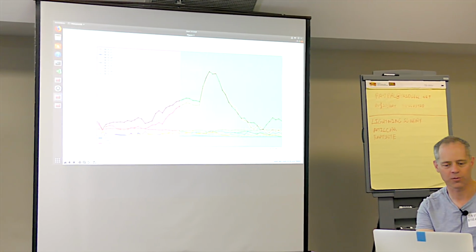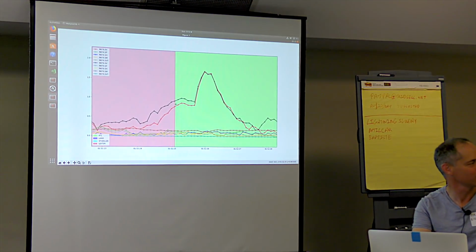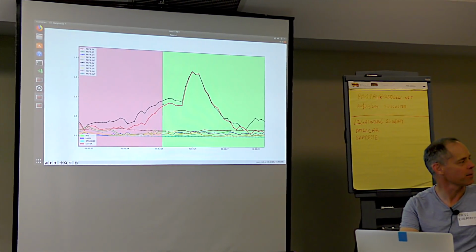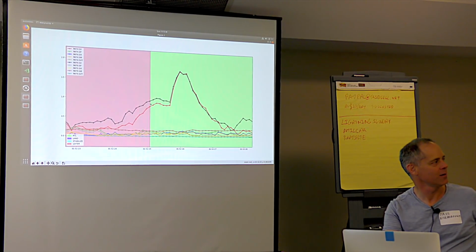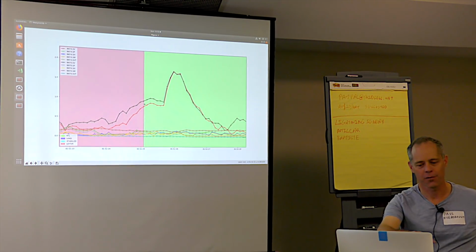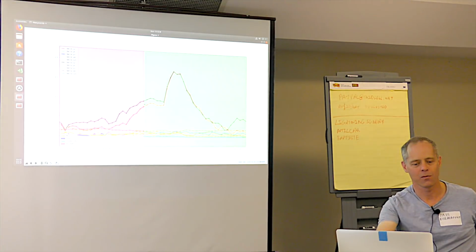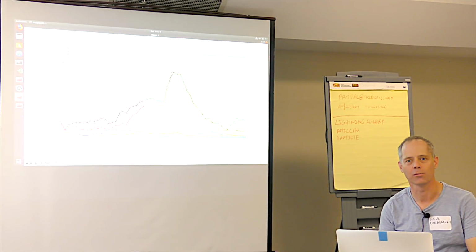Now, did the copter start to wander? By the time you get to about 0.8 or 1, the copter's clearly doing something. So we've had two consecutive events. On the first event, the operator didn't respond and left it in Loiter. On this second event, the operator reacted and put it into RTL.